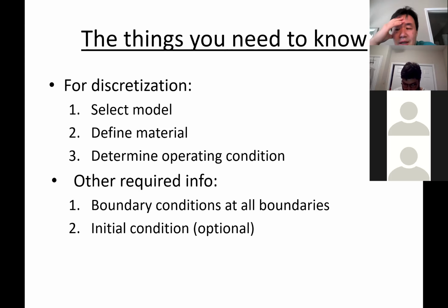Another one is called the initial condition. If you study an unsteady case, you have a partial time derivative in the equation, so it changes with time. If that's the case, you need to specify an initial condition: at the starting time, what the value is. Without knowing the initial condition, you can't do an unsteady simulation, right? And many times the initial condition is critical. For example, your weather forecast.